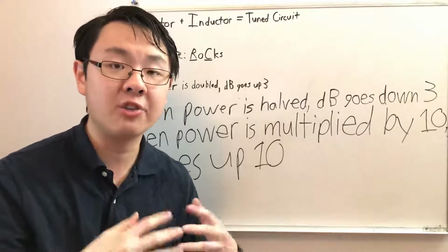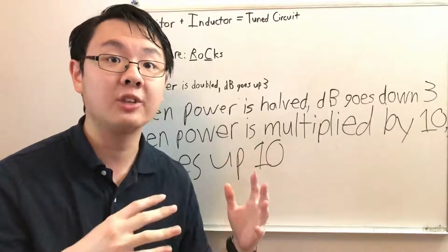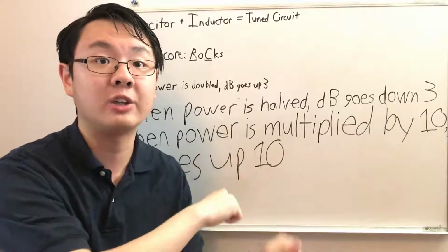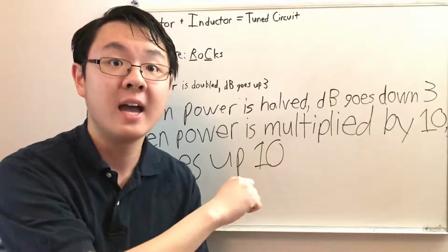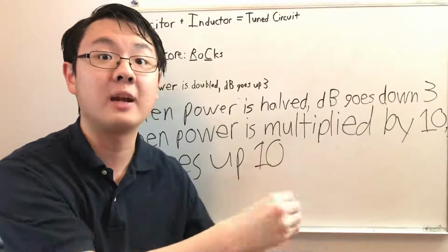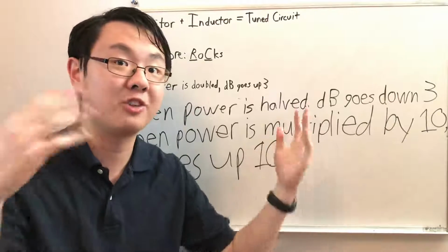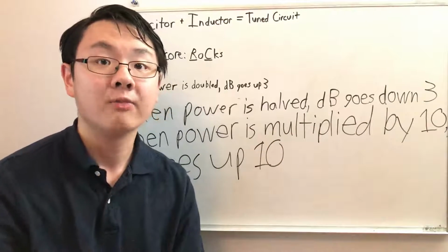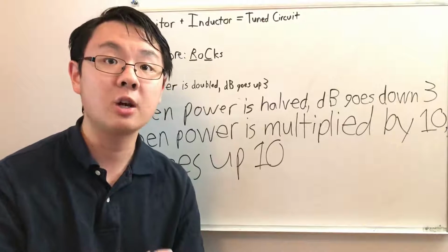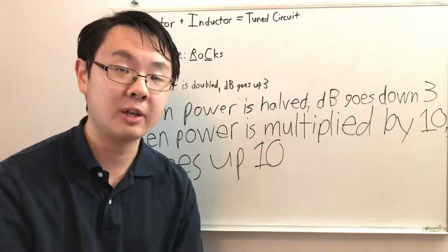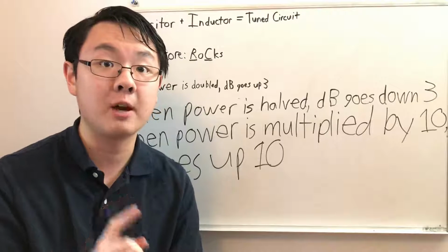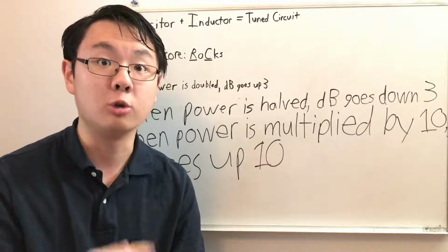It turns out that resistance meters are not built to handle high voltages. I plugged it into something directly plugged into the wall, and it was set to resistance, whereas it should have been set to voltage. Sparks actually lit up inside my multimeter, there were so many sparks, and it started smelling like smoke, and I fried my multimeter. The resistance circuit is not built to handle high voltage, only the voltage circuit can. I should have set my multimeter to voltage because that's what I was supposed to be measuring, but I set it to resistance. Make sure your multimeter is set to what you actually want to measure.